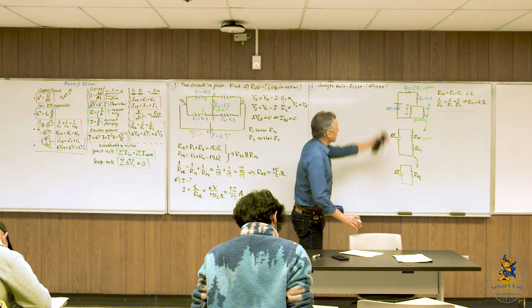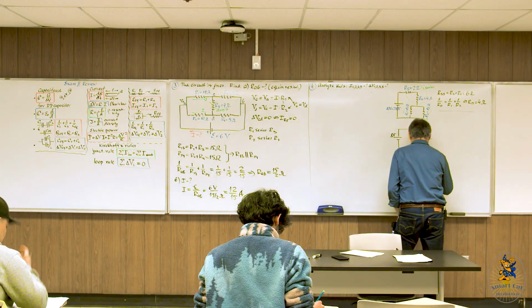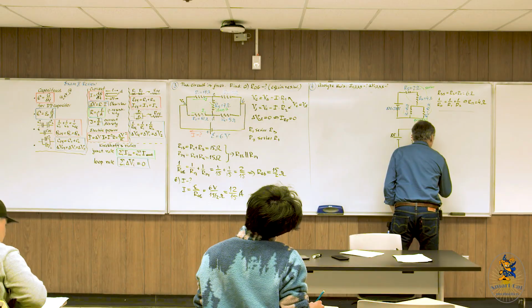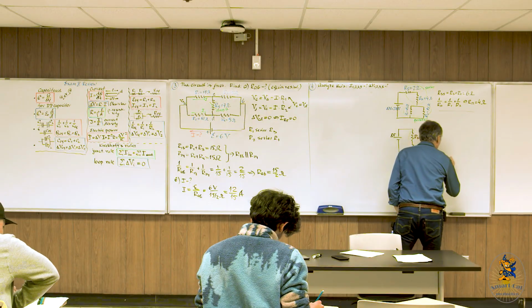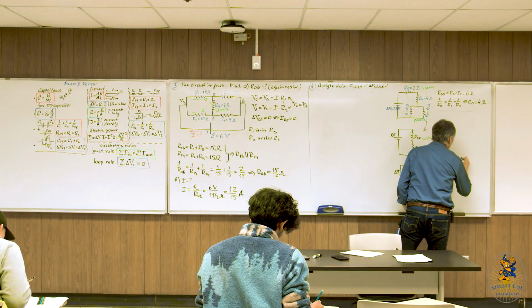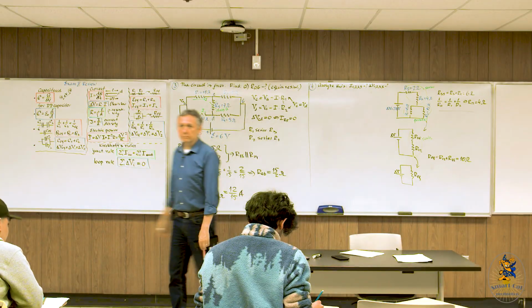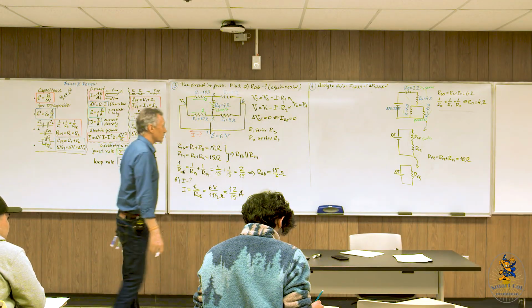So 4 plus 6, it will be 10, right? So it's very, very nice numbers. So R equivalent will be R1,2 plus R3,5. So it will be 10 ohms, right? Again, since we've done similar problems, I'm not asking much.